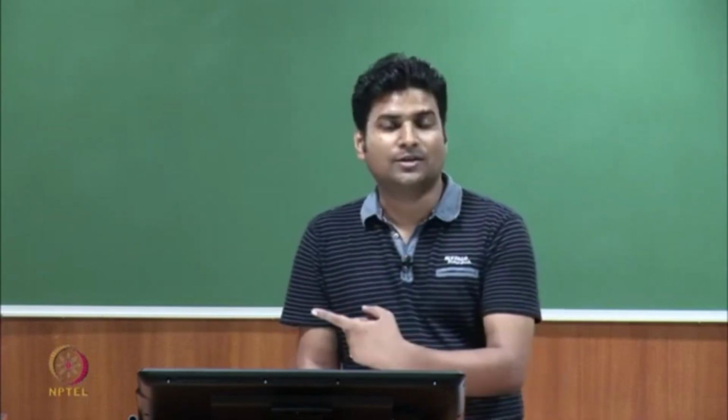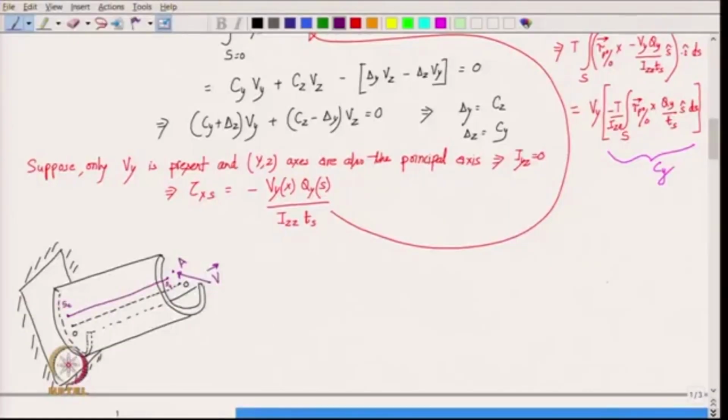And suppose we find out moment about the axis of shear center or moment about the axis of centroid, all of them should be 0, is not it? Now, in this case, let us find out moment about the axis of shear center, which is actually torque, right, because the axis of shear center is along the direction I, which is the axis of the beam itself, all right.